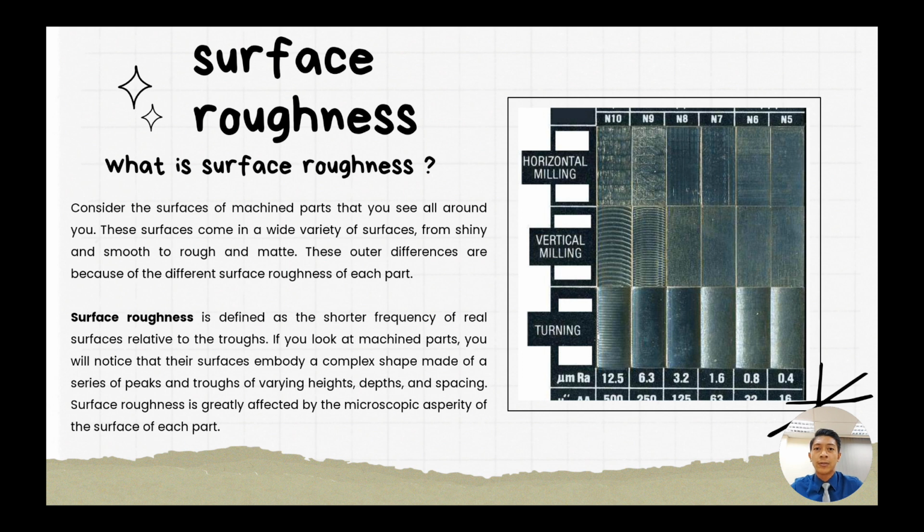Sometimes it can also be desirable to have a rougher surface finish on a part. For example, a seat post on a bicycle needs to have a high friction coefficient so as not to slip down when used. A rough finish cannot be achieved through machining. A secondary process like bead blasting or tumbling is required. There is no one way to achieve a particular surface roughness, as both the machining process and secondary finishing influence the surface roughness.